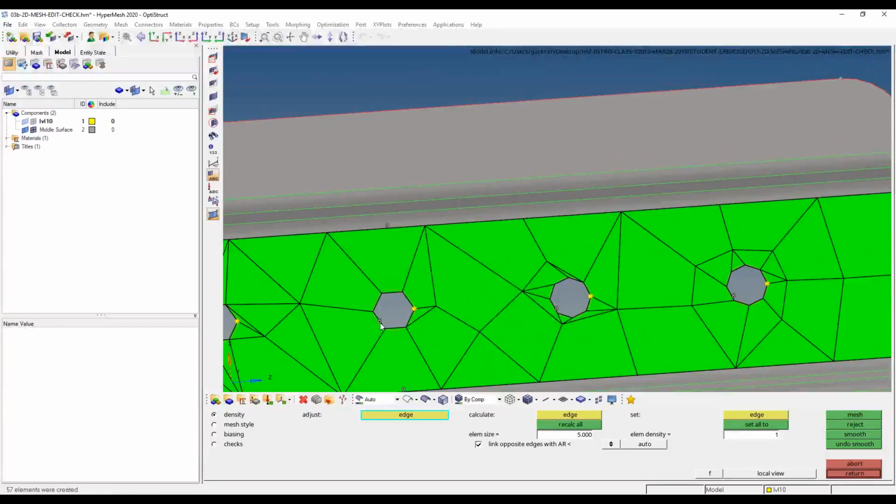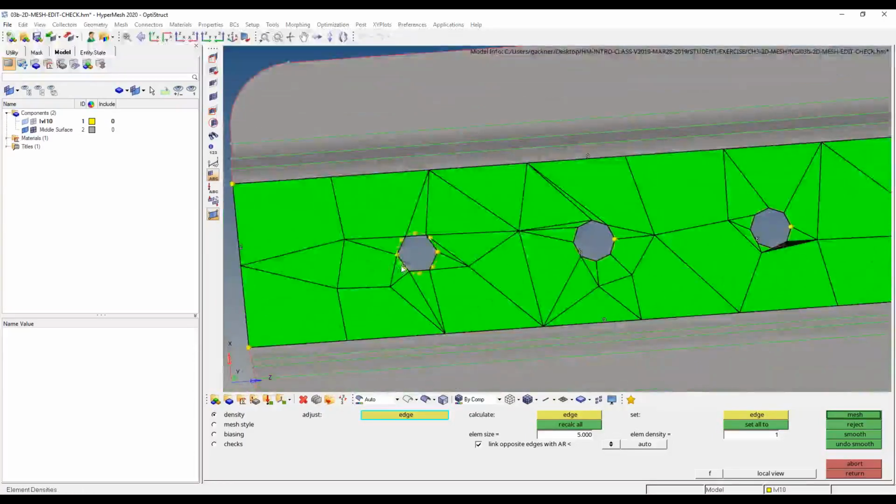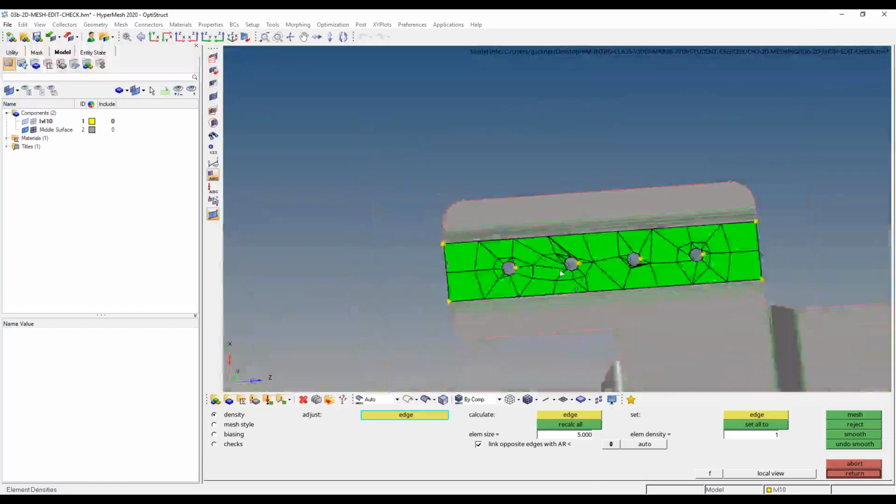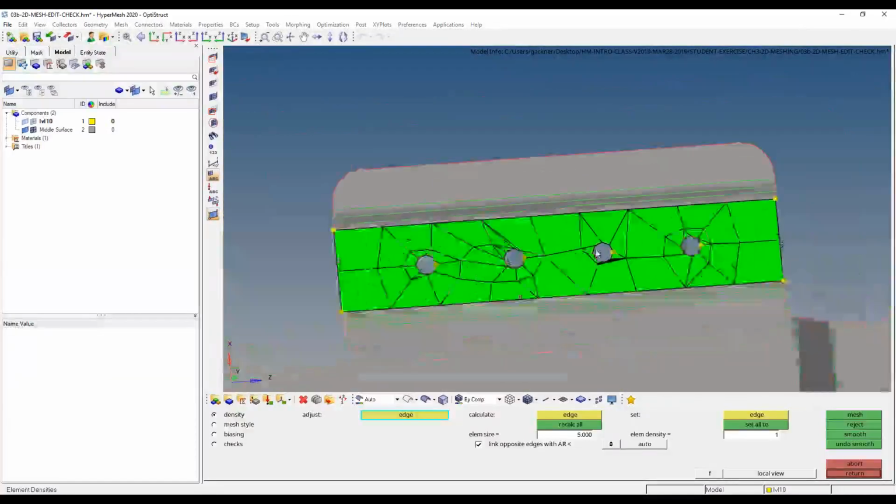But as we're seeing, and we learned earlier, as you increase the number of elements around a hole, the edge itself and the element itself gets a little bit smaller. And it's very common to consider elements as small as their smallest edge. That's one way you can think of element quality. So I think we'd all agree that this is really ugly looking for now.